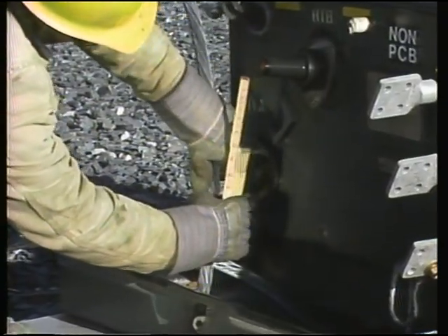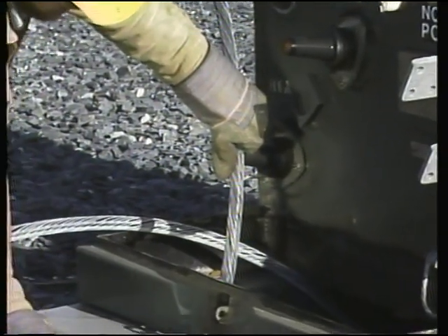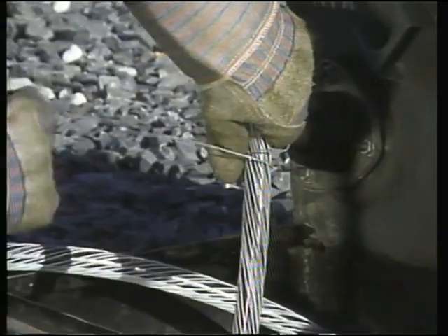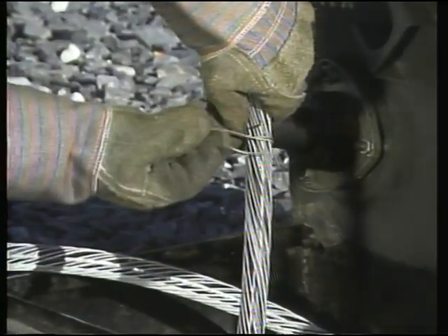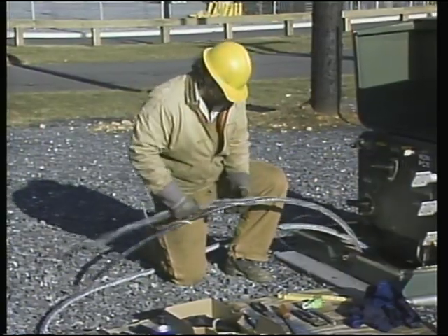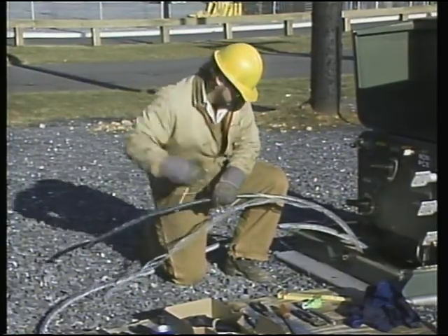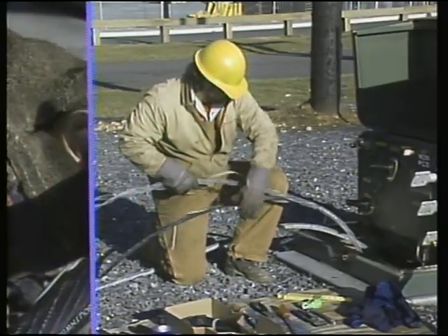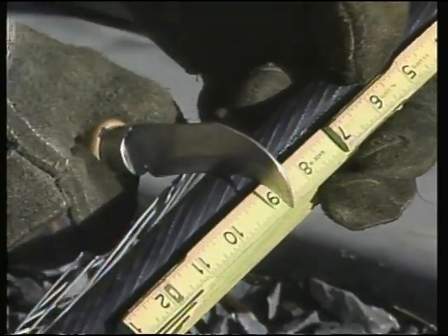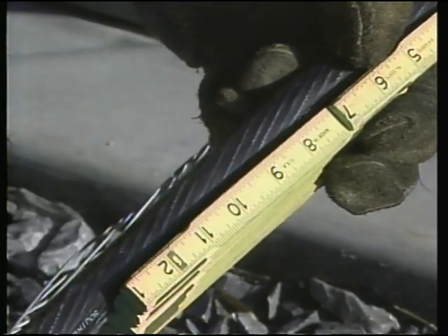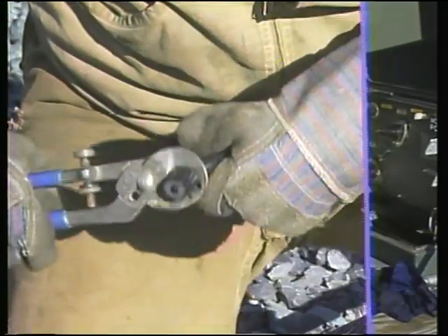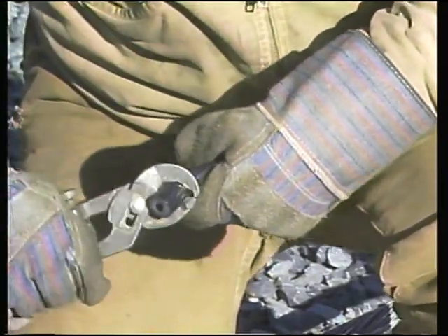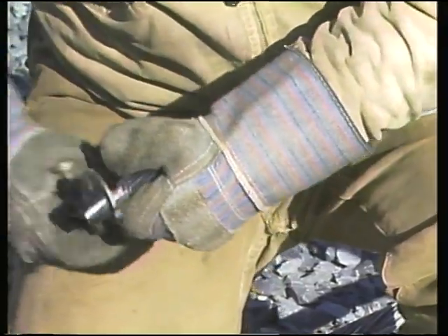The workman begins the termination by placing a mark on the cable at a point 9 inches from the center of the transformer bushing. This distance ensures that there will be enough of the concentric wires remaining to reconnect after the termination is complete. The concentric wires are then unwrapped and secured out of the way before the cable cut is made. Next, the cable is marked 9 inches from where the concentric wires were secured, and then cut. Then the conductor is exposed 1 inch from the cable end. This allows room for installing a compression connector.